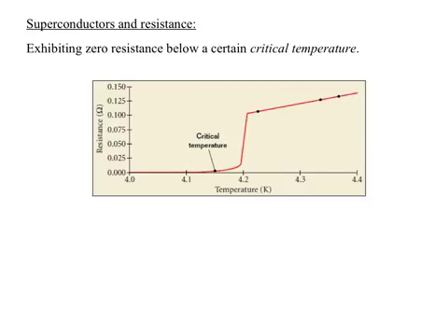It's because it's a variable resistor, it changes as you push more. There we go. So superconductors, and we spoke about superconductors and semiconductors that day, are things that exhibit no resistance. You could apply a current and there's going to be no resistance in the wire. That current will continue forever. It will not stop. Whereas if you apply a current and then remove the battery, it can't continue to be pushed forward. This is the equivalent of having no friction at all, like a frictionless surface. Superconductors exhibit this zero resistance when they're below a critical temperature. That's the key point here. And if you recall, we spoke about how temperature affects the resistivity of materials.